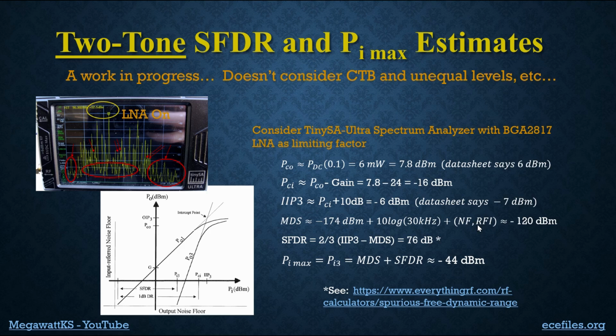Figuring out the exact value to use here is a little tricky, but let's just say we're operating outdoors, and so maybe it's about 9 dB, 9, 10 dB, whatever. Anyway, the first two terms, we had previously said that was minus 129 dBm, which you can calculate. I add 9 to that to get minus 120 dBm. So that would be this value here.